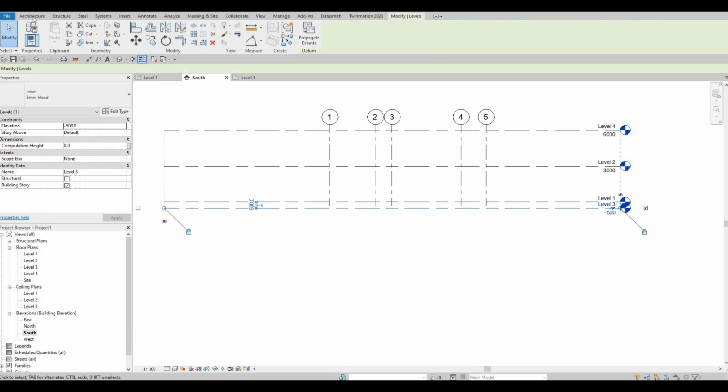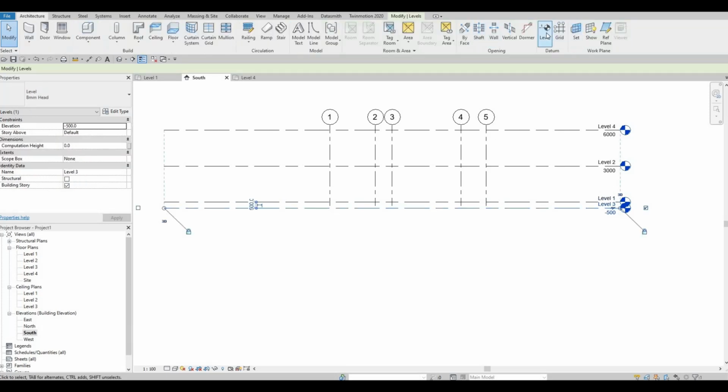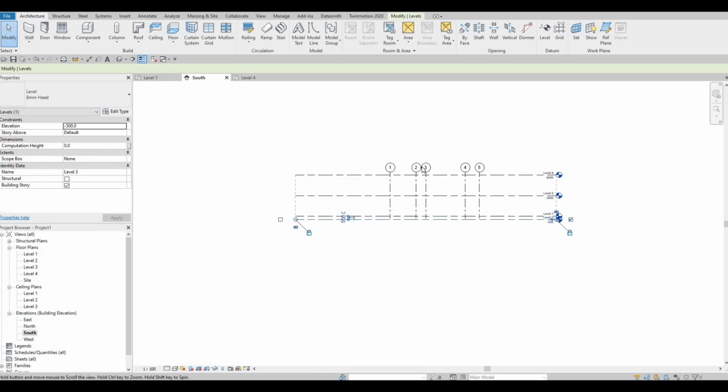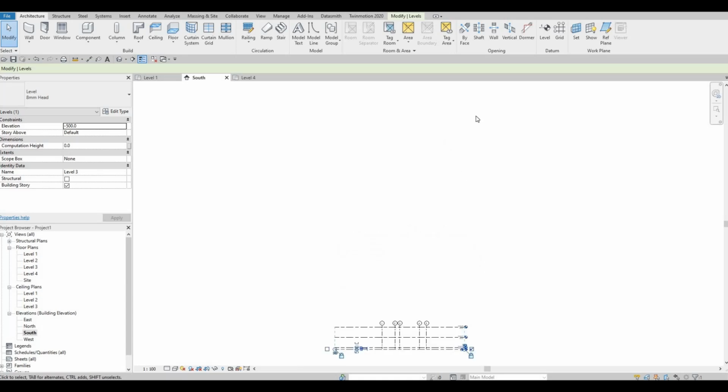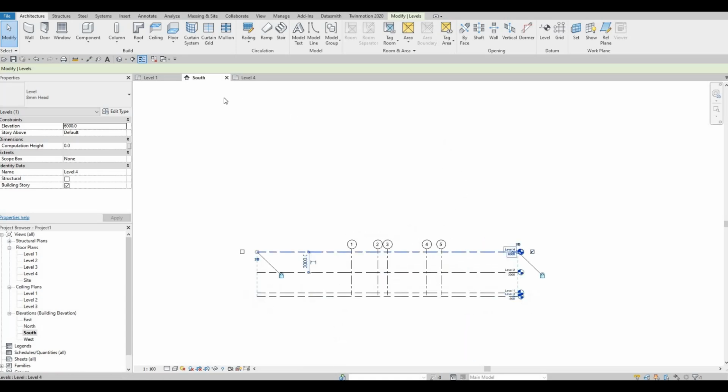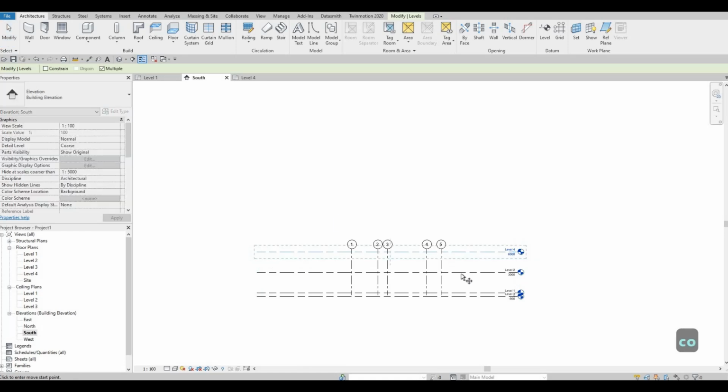The fast way actually depends on how many floors you're gonna do. For example, if you create a building, the copy command is much faster because you could just copy levels like that. So for example here, I'm just gonna type in CO, copy multiple times.